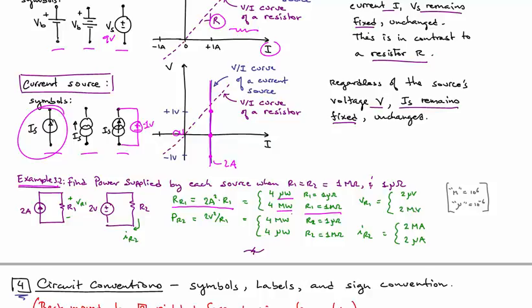And the reason is that when you push 2 amps through a 1 microohm resistor, it only develops 2 microvolts. So that's what the source has to work into. But when you push 2 amps through a 1 megohm resistor, you get 2 million volts. And now the source has to push 2 amps through 2 million volts.